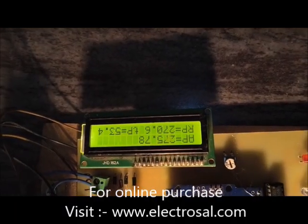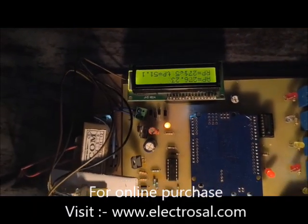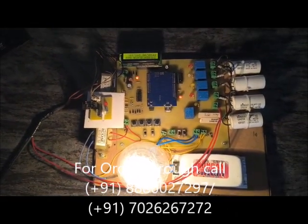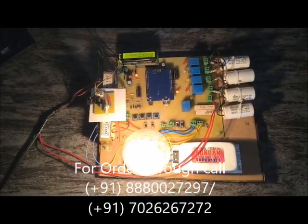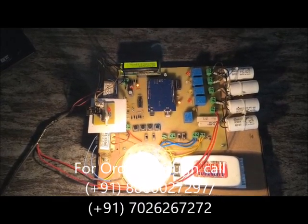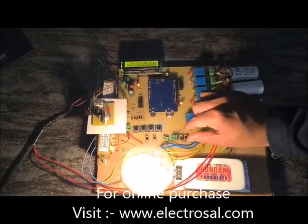Now at this stage, no inductive load is present. Because of this, the current lag is 0. As a result, the reactive power is very low and the real power and apparent power are almost equal. This condition occurs because no inductive load is connected and therefore no capacitors are switched on. Now I will switch on the inductive load.